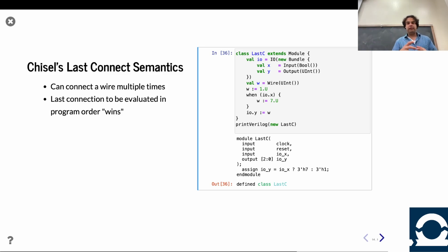And so a type is, I don't know the right word, maybe intangible, the way to kind of think of it, right? And so a wire can be of type uint. So wire, because it's hardware, needs to be of a chisel type. So it can be of type uint, it can be of type bool. If I have a Scala int integer or a Scala Boolean, those are not going to be able to be put into a wire unless I cast them.